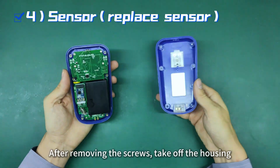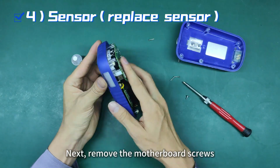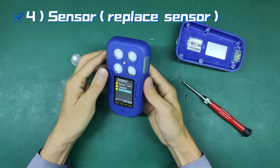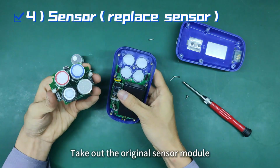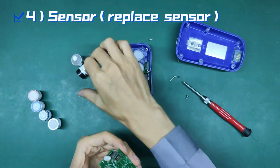After removing the screws, take off the housing. Next, remove the motherboard screws. Enter the menu and find Seek Sensor. Take out the original sensor module. Pull out the 4 sensors one by one.